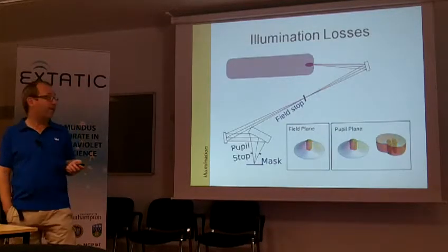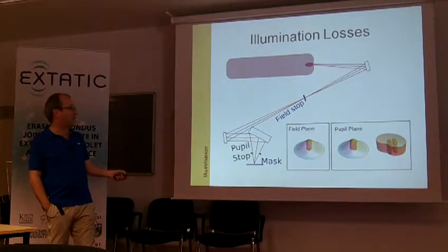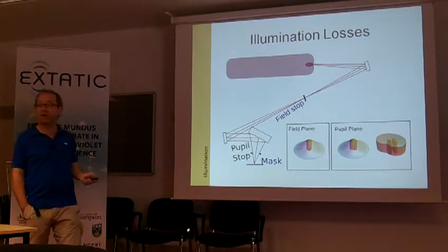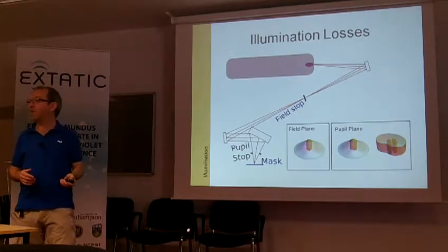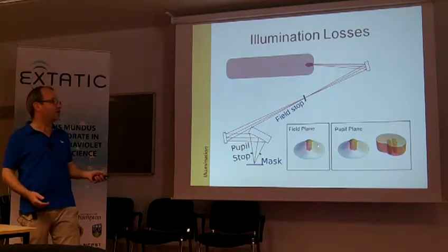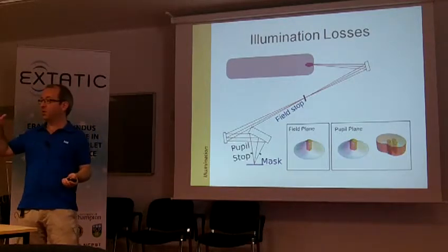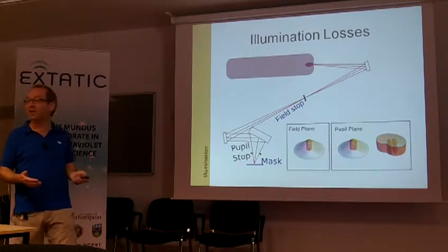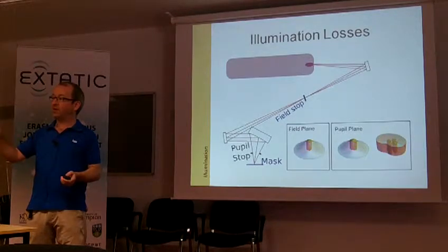Can you please explain that again? So, in order to have uniform illumination on the mask here, if we produce a light source with a more or less Gaussian output, and the illumination uniformity for imaging at the surface that they require is, let's say, 5%, or a few percent, then the metrology system manufacturers like Carl Zeiss, for example, can't use the photons that are further out in our Gaussian source. They need to take a section of the source which is sufficiently uniform to allow them to illuminate the object uniformly. So they chop the top of the source off, and they only use the brightest part of the source that's sufficiently uniform for them to illuminate the field that they're trying to image.